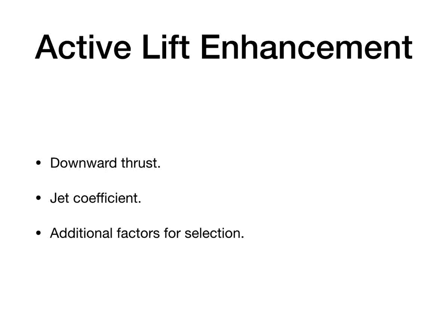In all these approaches, there are additional factors that affect the selection of one over another. The internally blown flaps require internal ducting that can be heavy and result in internal momentum loss. The upper surface blowing blows hot exhaust air over the wing surface. So this generally requires that portion of the wing to be covered with a heat resistant material like stainless steel, which adds weight.